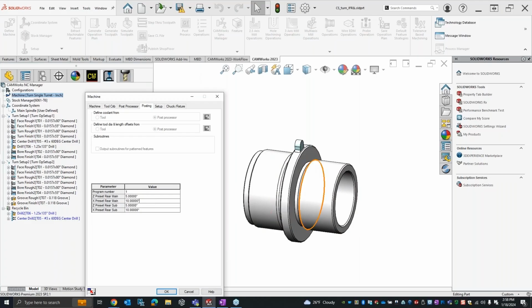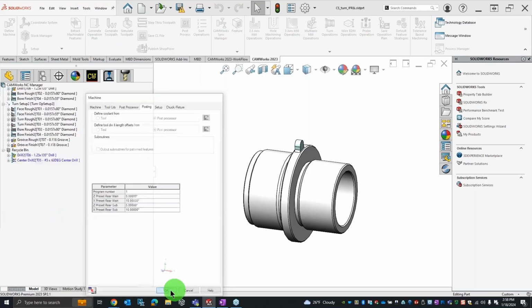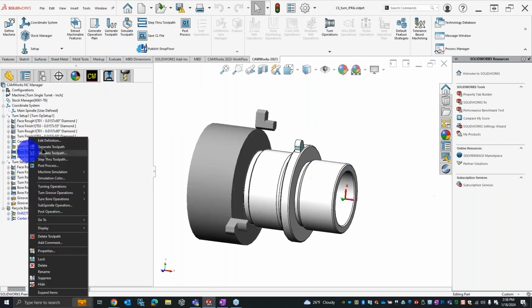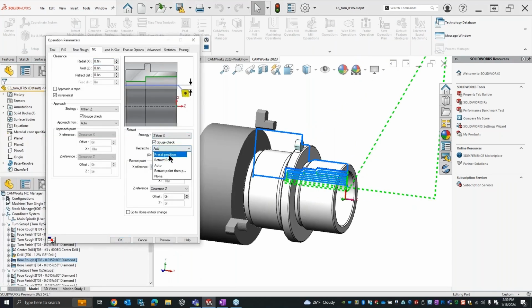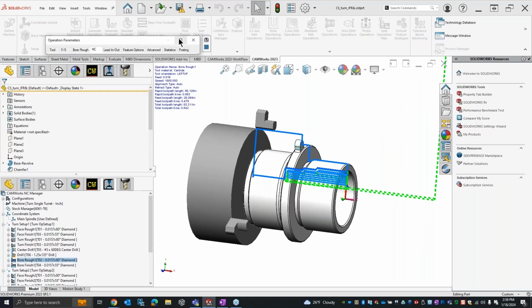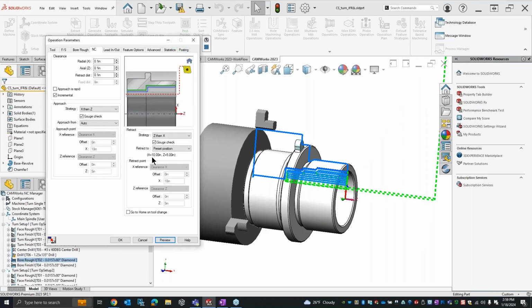So every time there's a tool change, it goes to this position here. The point of this is it's kind of like a go-to-home thing, right? But instead of making your tool go all the way home to the tool change, you can pick a closer point where it's still safe to do the tool change. So you can make a point that's still safe, but it doesn't have to go all the way to the machine home position, and then you can do the change there. So that's what that is. If I go into the boring one, that should be what preset does. You see it right there? It's going to X10, Z5, but I think the output will actually be X20, Z5, right?